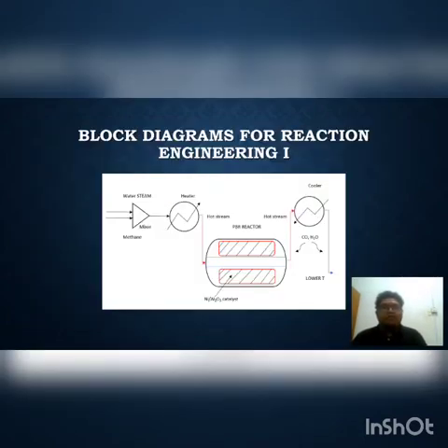This is the block diagram for the reaction engineering part. First, we obtain methane from the membrane separator part, and we mix it with water steam and transfer it into a heater. The heater then will elevate our reactant temperature level and send it to the PBR reactor. The PBR reactor will have a heterogeneous catalytic reaction and yield carbon monoxide and hydrogen as our main product and send it into a cooler. The cooler then will reduce our temperature so that the carbon monoxide and hydrogen can be used in other parts of the plant.